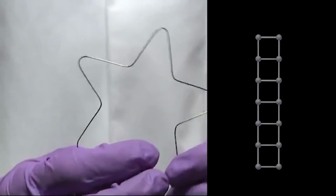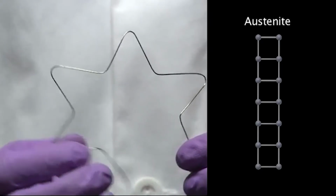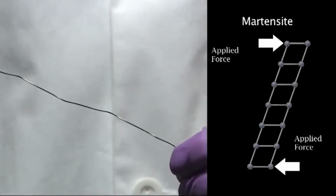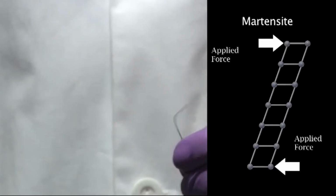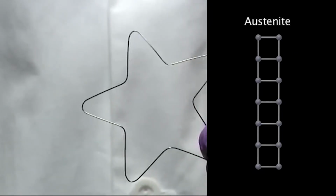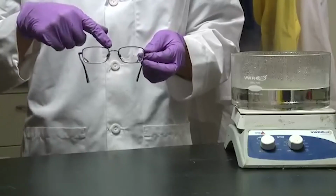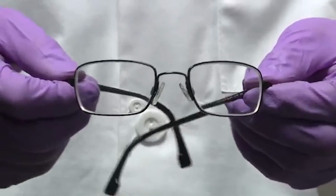This material is a slightly different composition, so that at room temperature it is in the austenite phase. If we stress the material, we can force it into the martensite phase, and this will change the shape. But if we release the stress, it goes right back to the austenite phase and the original shape because that is where it is stable at this temperature. You may have seen this before in eyeglasses that can be stretched without being permanently bent.